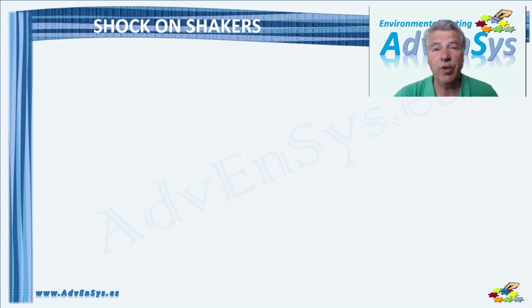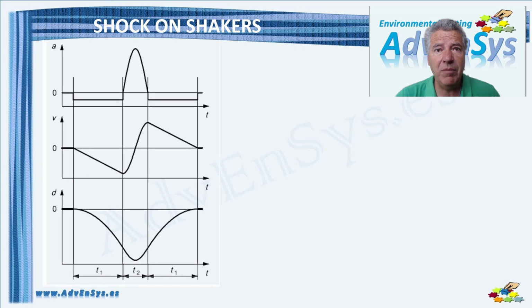Whenever we can, we try to reproduce classical shock using shakers. With shakers, we get a more precise and accurate acceleration waveform. Two consecutive shocks are practically equal, and we can generate repetitive shocks at a defined rate. All these features are extremely difficult to reach with a shock machine.